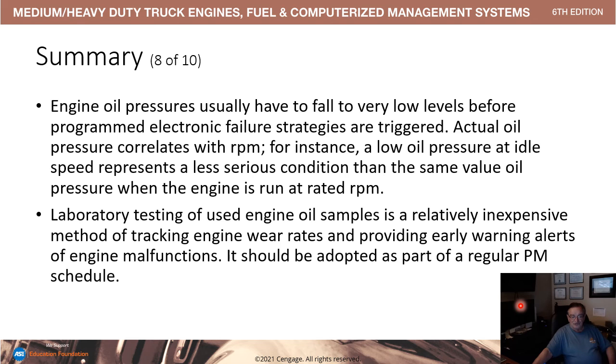Laboratory tests using engine oil samples are relatively inexpensive for tracking engine wear rates and providing early warning alerts on engine malfunctions, and they are adopted as part of the regular wet PM schedule in pretty much all fleets. Independents and owner-operators don't necessarily adopt the same practices as the larger fleets do.